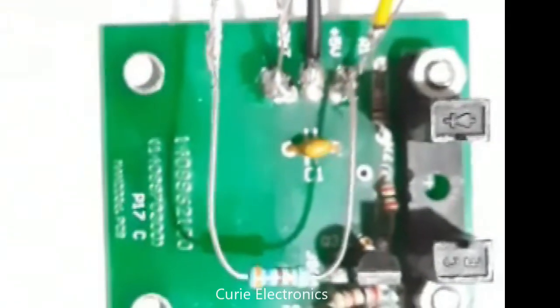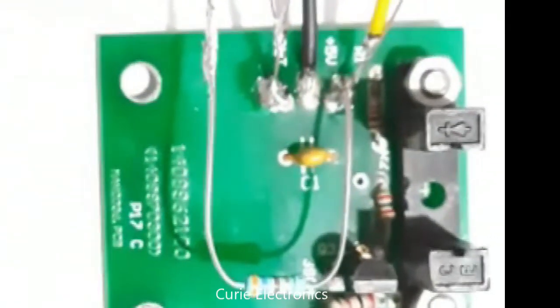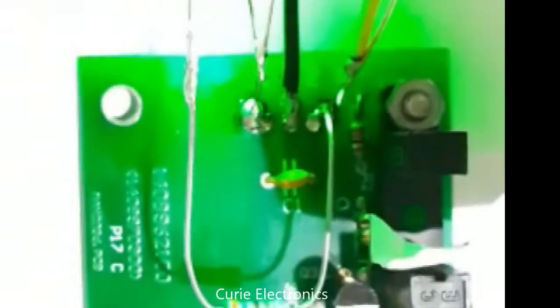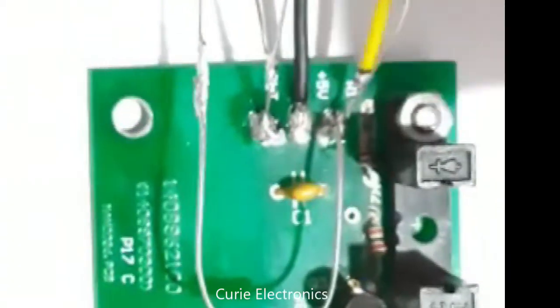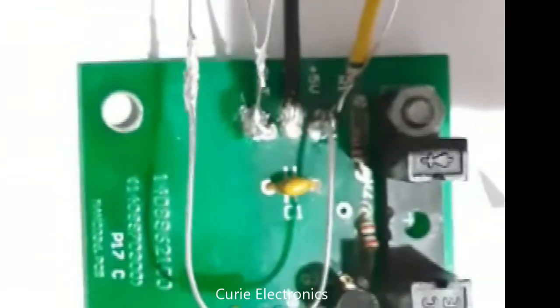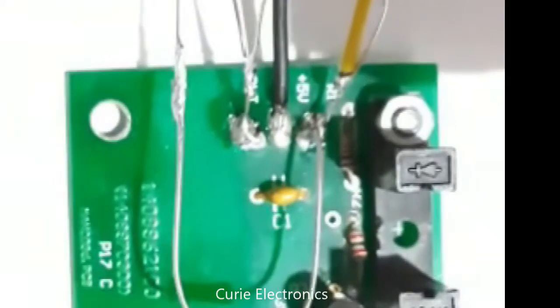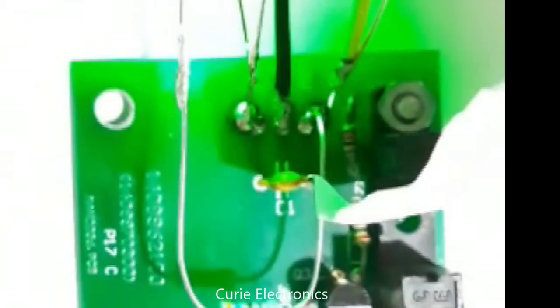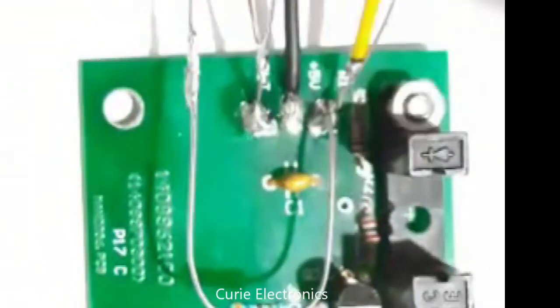I have connected a pull-up resistor and LED to show you. So now if I block with a paper, see the LED turns on. That is because it is staying at high. Initially the output is high, but later on it is changing to low. When the output goes low, the LED turns on.